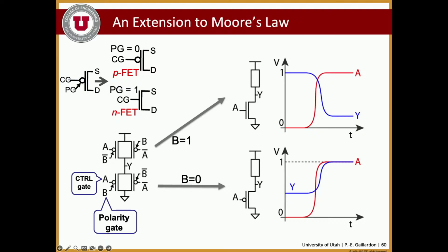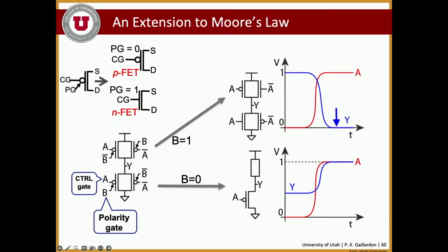But now, let's try to apply our circuit tricks and find a topology that will allow for not having pseudo-logic, but having complementary MOSFET type of structures, and also finding a way to always have a PMOS in the pull-up network and an NMOS in the pull-down network. Just standard circuit design. What happens right here is that we're going to restore our logic levels to where they should be, and that's pretty nice.